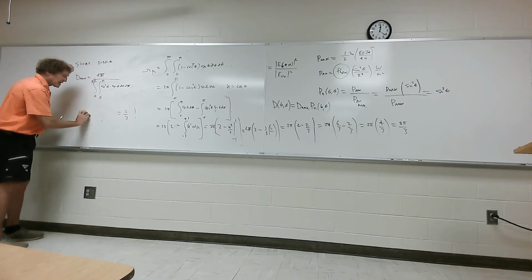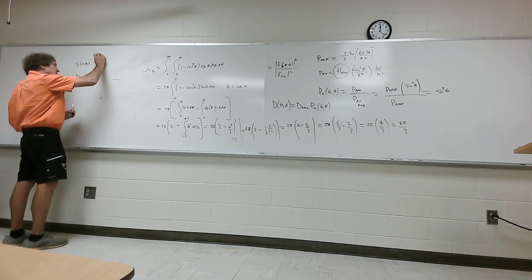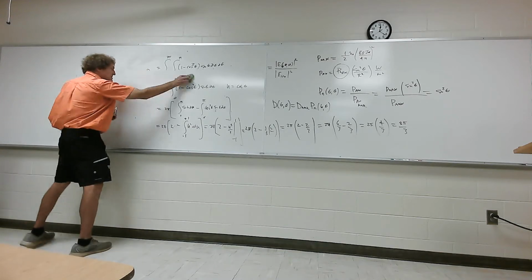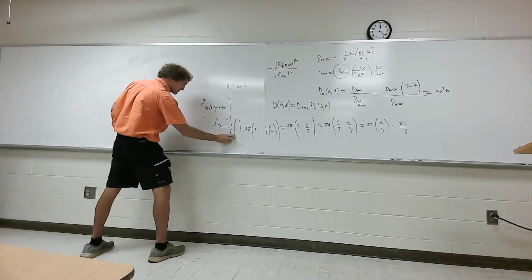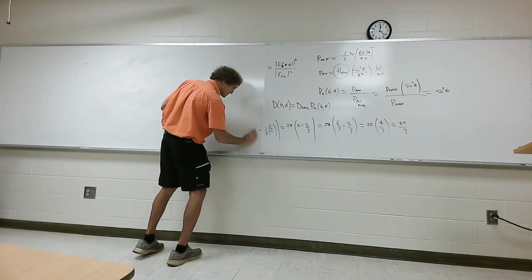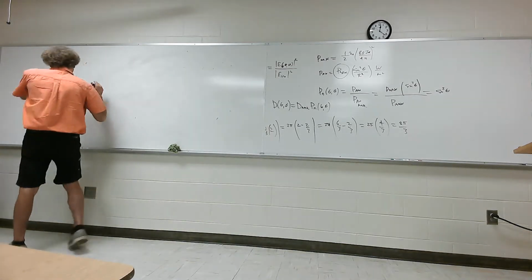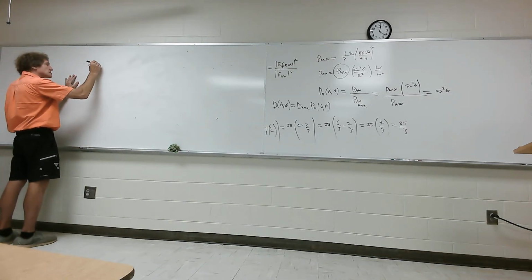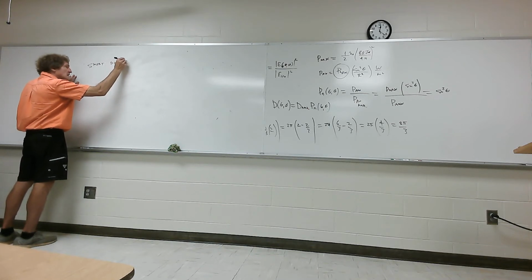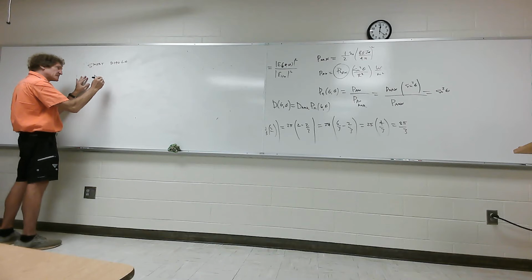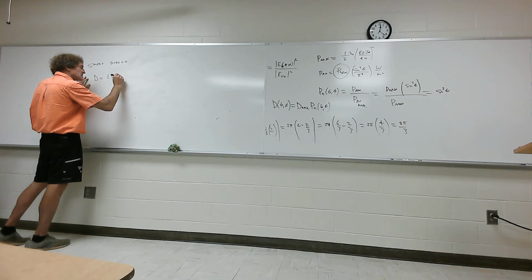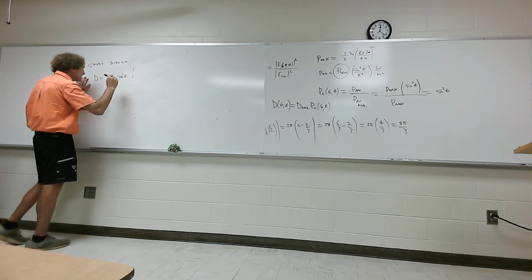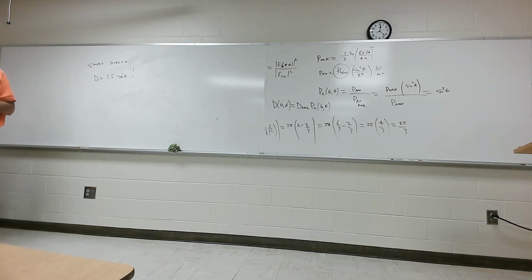Okay, so that's D max, and therefore I can say the overall directivity, please write this one down, for a short dipole. So this is the directivity for a short dipole. Now you can say D is D max, or 1.5 times the normalized power density, which is sine squared of theta. And that is the directivity for a short dipole. Y'all follow me?